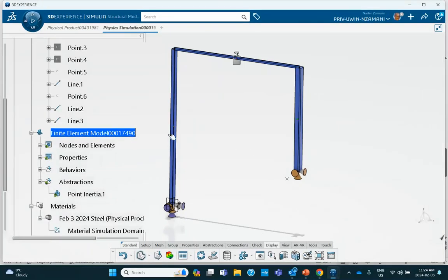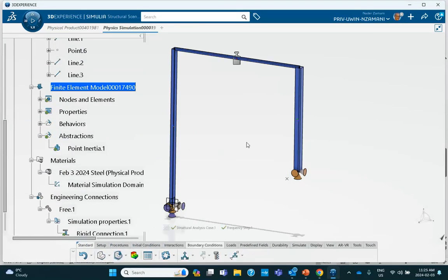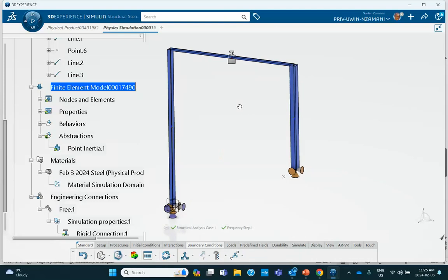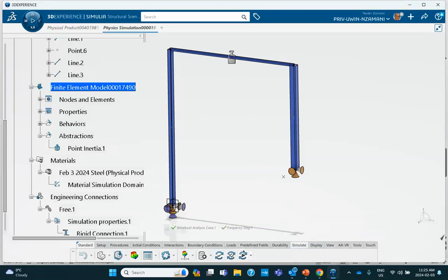Okay, good. So now we're going to go back to our scenario creation that we just started. Okay, we put the restraints here, and that's pretty much it. There's nothing else we need to do. We have the restraints. We created the inertia, mass inertia. We may declare this thing as rigid. They both referring to the same reference point. And let's go ahead and run it. This is a quick model check. This is a simulation check.